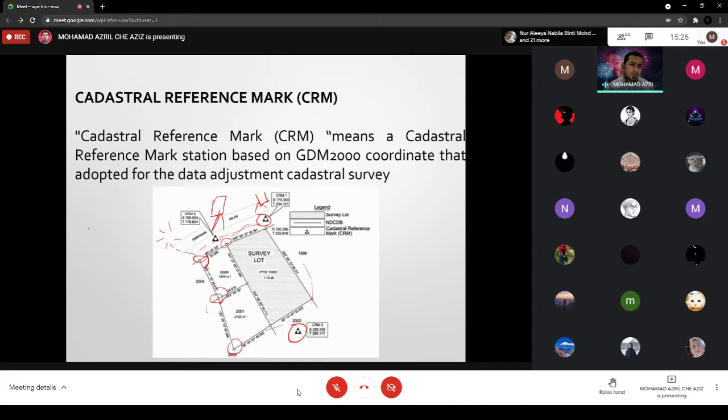when you carry out the GPS. Okay, so the cut-off angle means here, any data or signal that comes at 15 degrees, in the part that I have drawn, it will be removed.